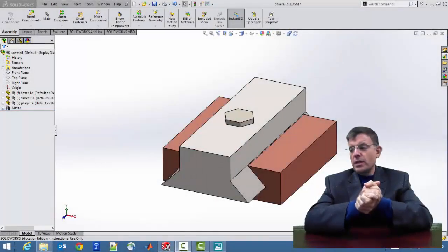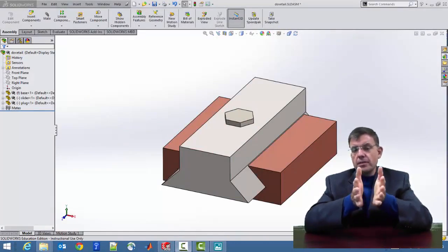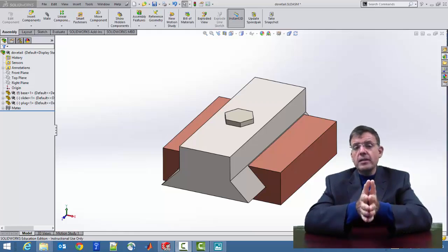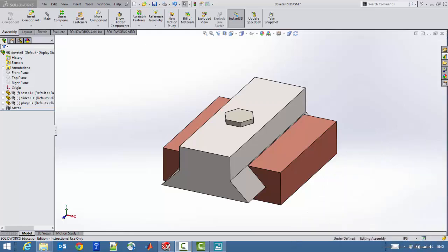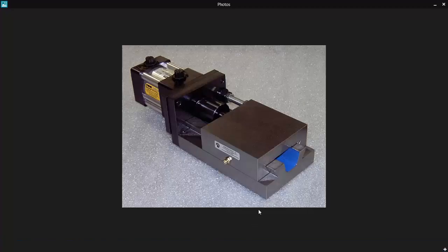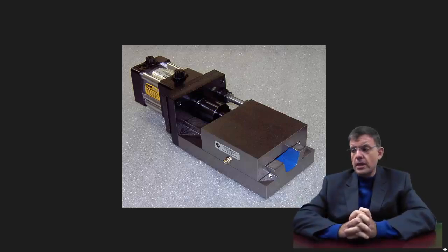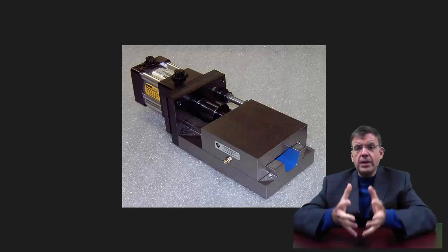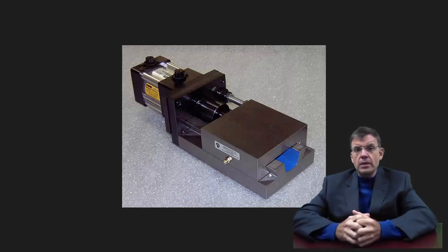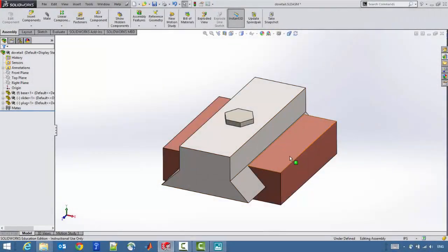Okay, let's practice a little more with another example here. This is going to be the example of a very highly simplified dovetail slide. Dovetail slides are one of many different types of linear bearings that exist, and these ones are particularly useful because they have a very high surface area. So they tend to be stronger. You find them in certain machine tools. They're not intended for very high rate, high speed, high cycle type of applications, but rather when you need a lot of stiffness.